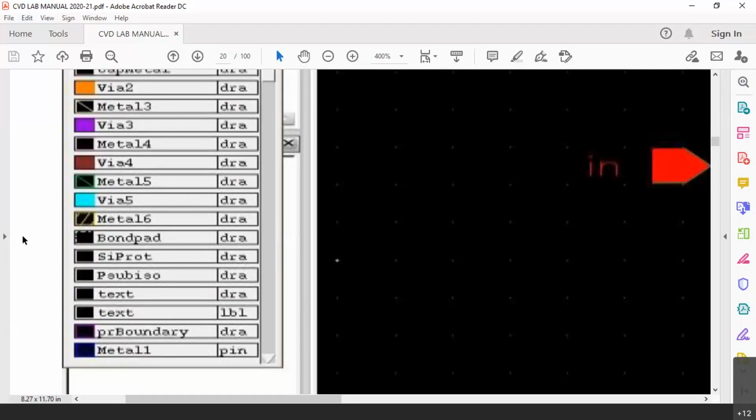That packing can be ceramic or plastic packing. That packing is required because our fingers are big, whereas the chip is so small. We cannot handle the chip through bare fingers. That is why such packing needs to be done. After the packing, we either solder it to the PCB by means of the soldering lead, or using a hot air gun if the package is a BGA pack, if it is a ball grid array pack. Using a hot air gun, the pack is bonded to the PCB.